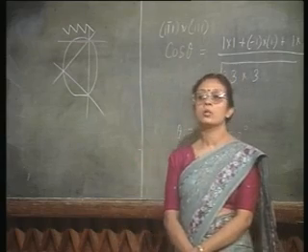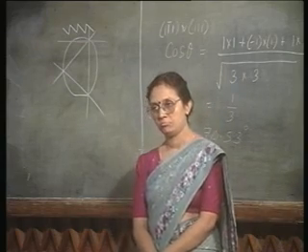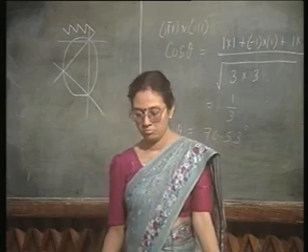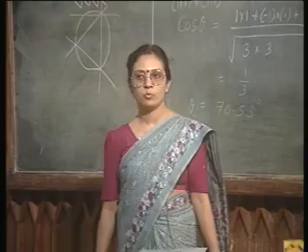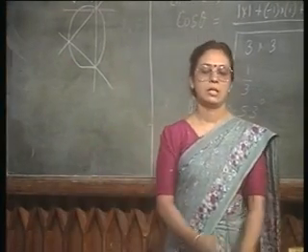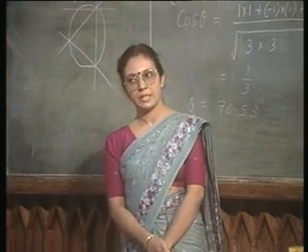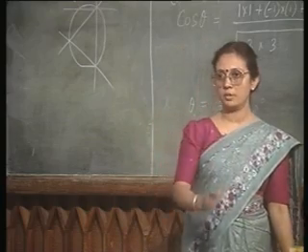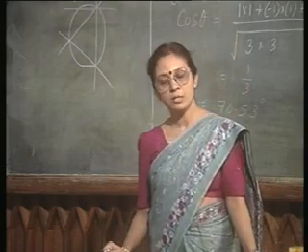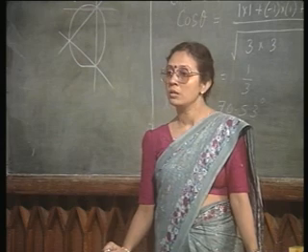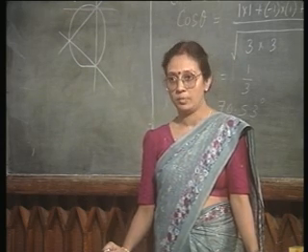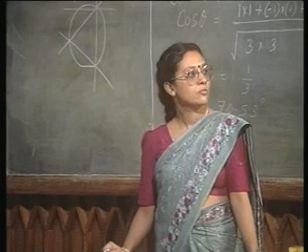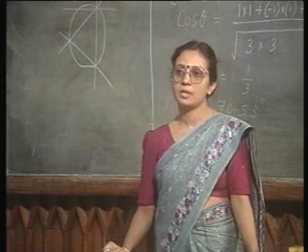If I have 110 silicon, it is going to be very interesting. Again you see the first point is common, when I am cleaving the cleavage plane is going to be 111 planes. I leave it for you to work it out, find out the angle cos theta.